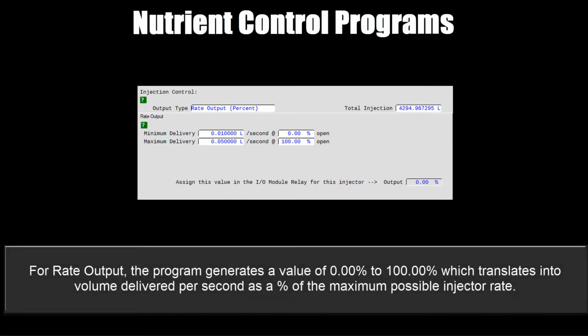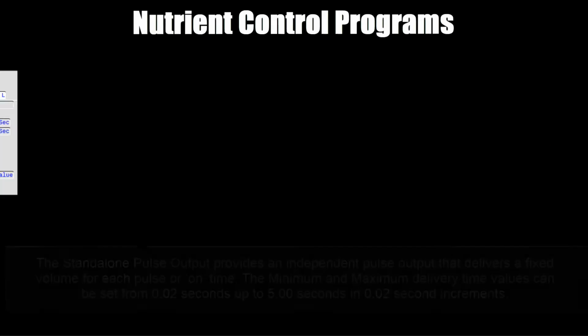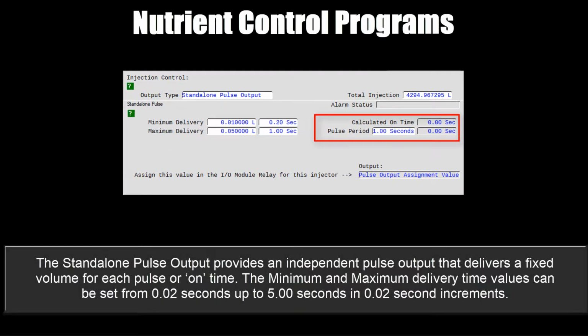For the rate output, the program generates a value of 0% to 100%, which translates into volume delivered per second as a percentage of the maximum possible injector rate. The standalone pulse output provides an independent pulse output delivering a fixed volume for each pulse or on time.